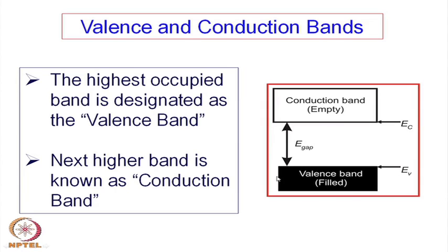You also remember that there is no axis here. Whenever we draw a band diagram, we never give a horizontal axis. What is the horizontal axis? It is immaterial in fact. We are talking about only the gap here. The horizontal axis does not have any significance here. In fact, this gap is along a particular vertical line.